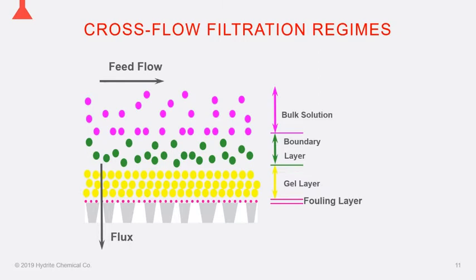Also, that higher flow creates that turbulence that we discussed last week. Remember, turbulent flow as it goes across that mesh screen helps to remove that and reduce it. It doesn't necessarily all remove, but it minimizes and reduces the level of fouling. So the element will run for extended runs versus very short life from a conventional dead end filtration.